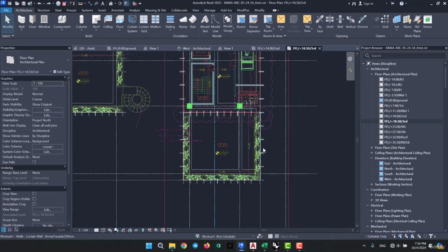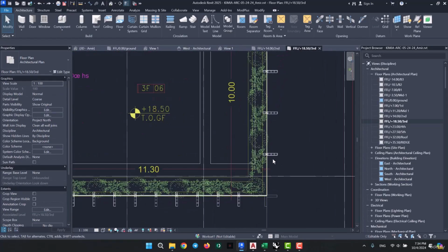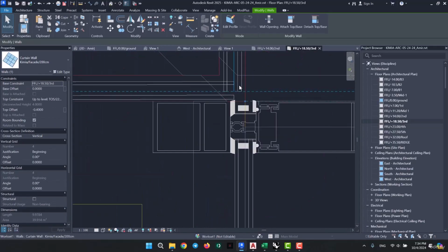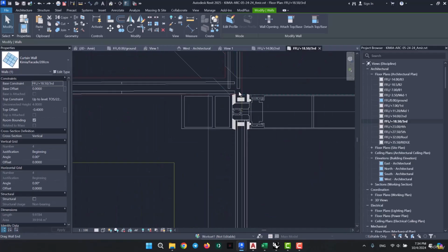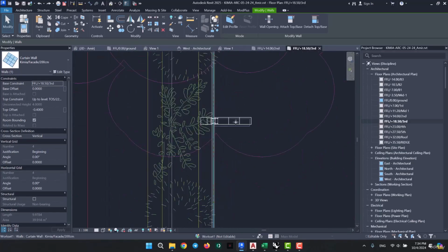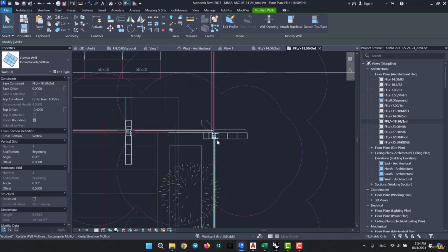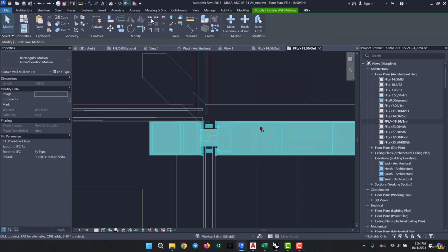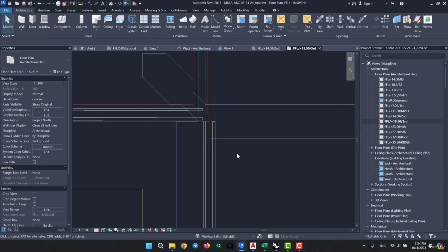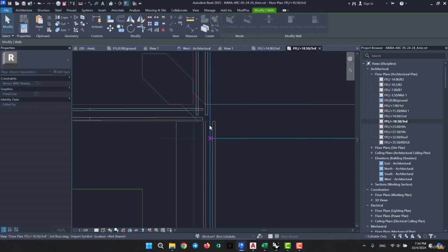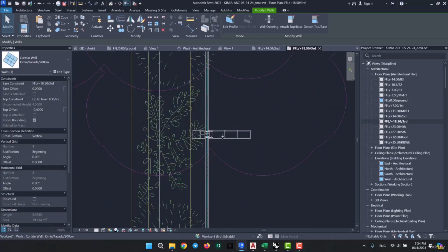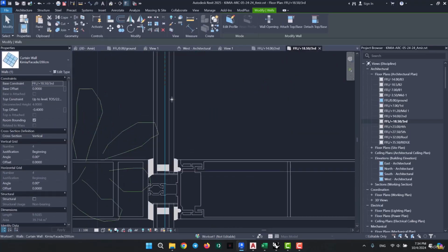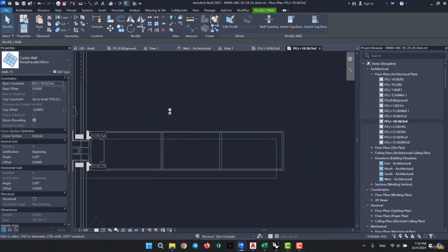Now, as for the right side of the terrace, which is in fact the right side from our point of view, we're going to have to fix the mullions. And so I see that I started this one from here, and the first thing I need to do is to remove this first mullion. There we go. Then I'm going to bring this grid lower. And as for this mullion down here, we're going to have to move it a little bit to the left. So let's see how it goes.